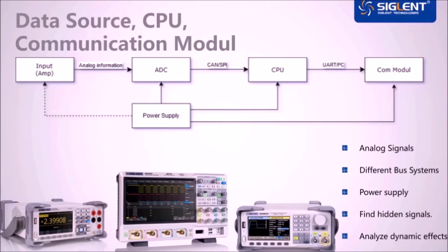Within the DC part are a lot of different tasks for the test and measurement equipment. Usually one would like to take a look at the buses with the protocol analyzers or simply simulate the different sensor states with the signal generator. You see, this part contains a lot of basic stuff, but it's very underestimated. Especially a bad power supply is often a major problem for wireless communication. And it's usually considered as one of the last possible reasons for a problem. Since you have many different tasks here and want to build a reliable basis for your system, your tool should be flexible and precise enough to fulfill all your requirements.